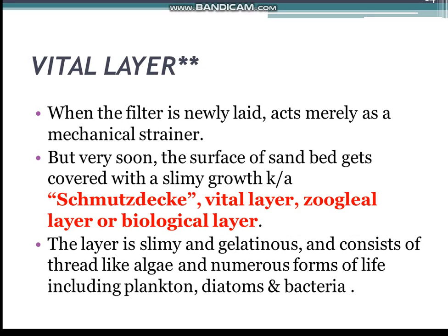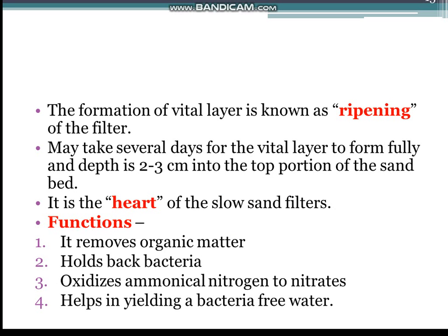Vital layer. When the filter is newly laid, it acts merely as a mechanical strainer and cannot truly be considered biological. But very soon, the surface of the sand bed gets covered with a slimy growth known as schmutzdecke, vital layer, zoogleal layer or biological layer. This layer is slimy and gelatinous and consists of thread-like algae and numerous forms of life including plankton, diatoms and bacteria. The formation of the vital layer is known as ripening of the filter.